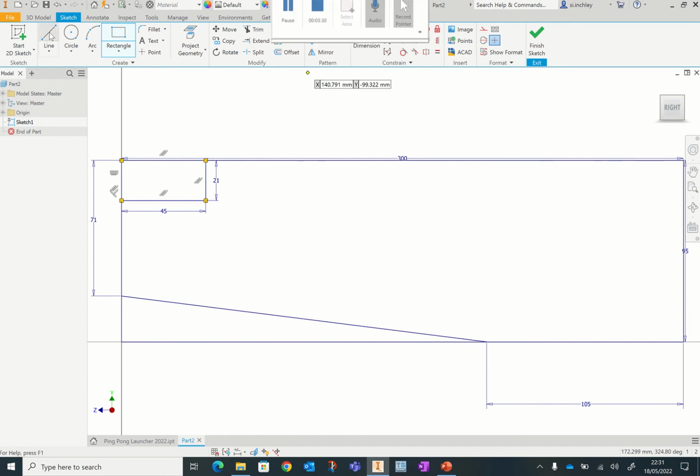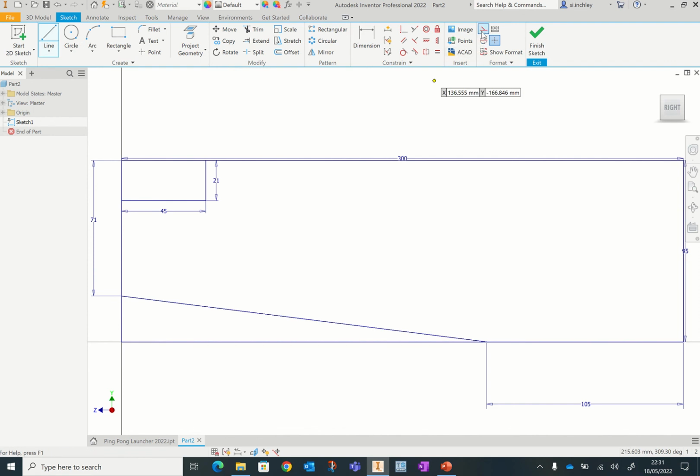I want to select my line tool, but I also want to select this button here called construction. And this doesn't do much, but kind of gives me a marker line. So I'm going to click not on the center line, so be careful not to select that. Come up about 1/3 of the way down, click. Don't click and drag, click and kind of let go and move your mouse, and then click on the other line all the way across.